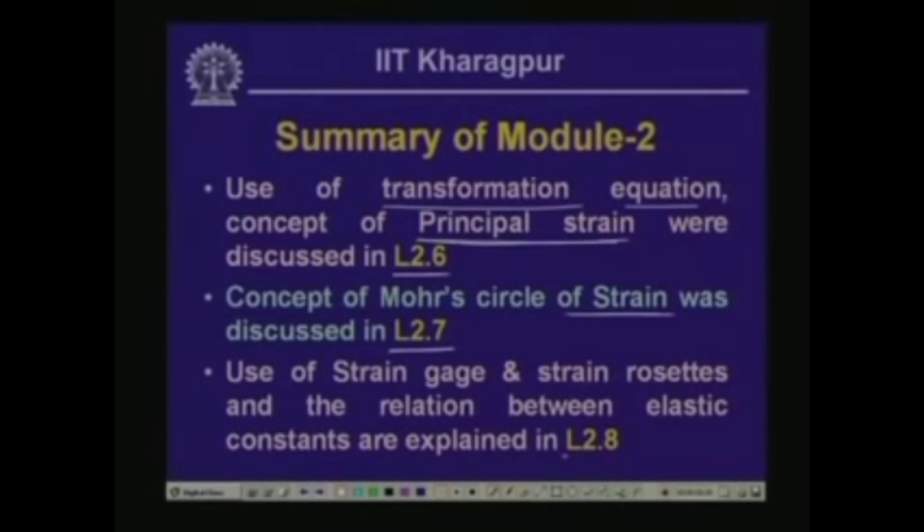And the last lesson, that is the 8th lesson, which we discussed previous to this, we had introduced the concept of strain gauge and strain rosettes. At any point, as I have told you, it is easier to measure the strain and it is difficult to measure the stresses when we talk about a stressed body. Hence, we can measure the strains and from those measured strains we can compute the stresses.